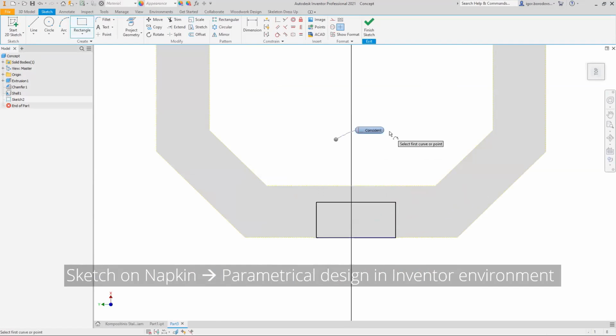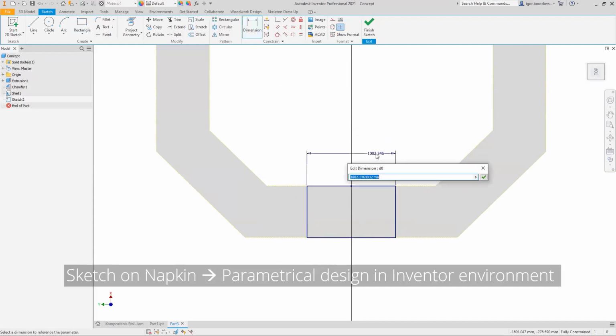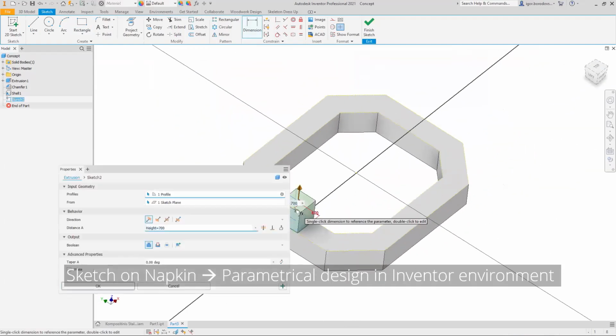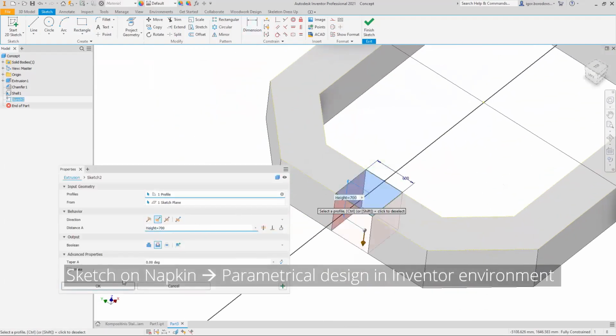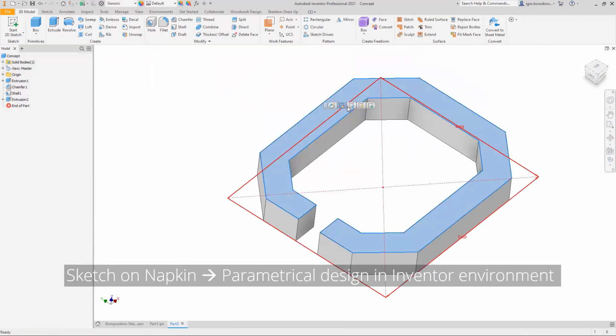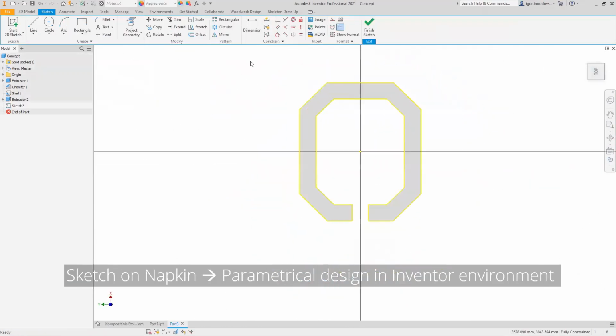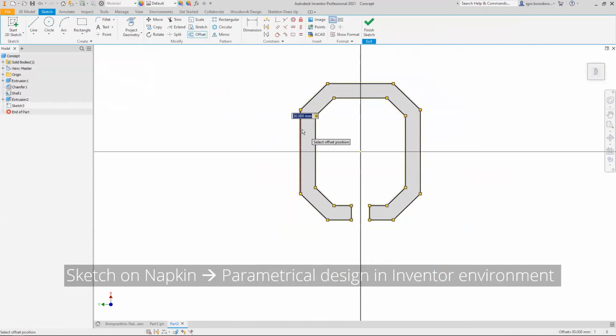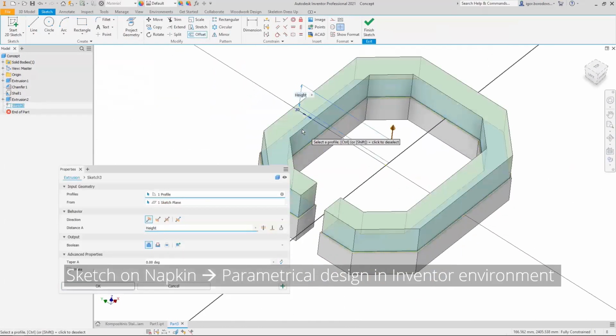Having that in mind, we can think about whether our design decisions were right, and if needed, we can easily change it. Because this initial design can take, let's say, maybe 2 to 5 minutes. So you can quickly build this 3D napkin sketch in Inventor, and then you can see if your design intent really works as you expect.